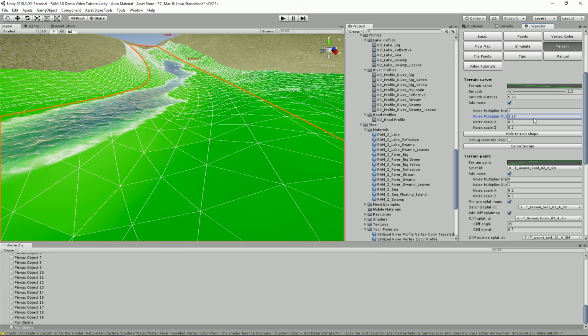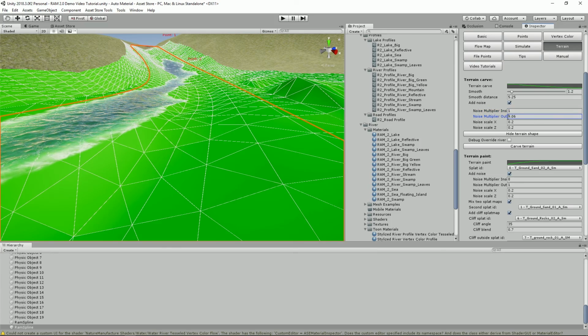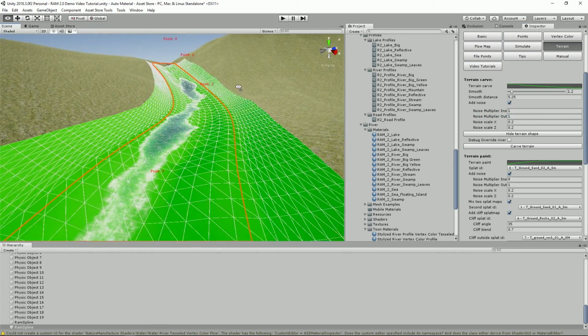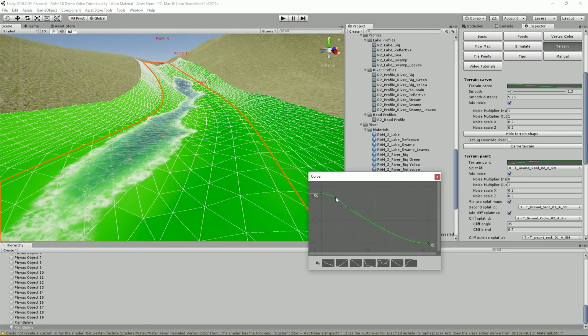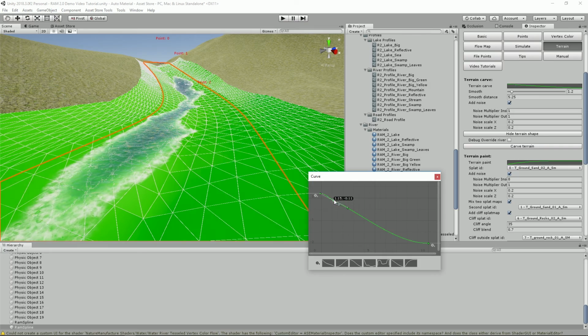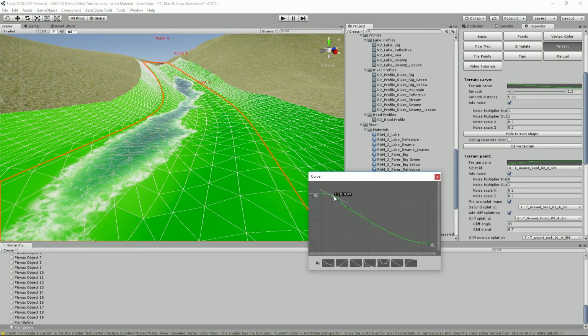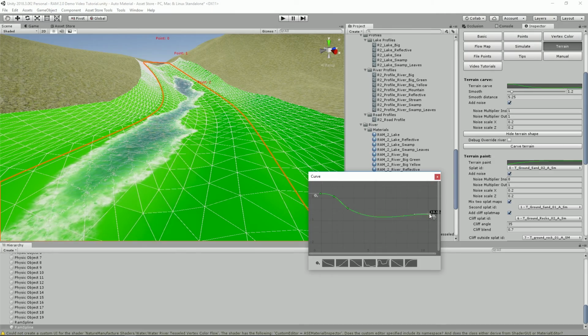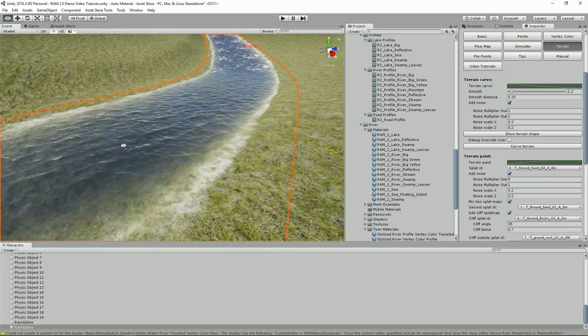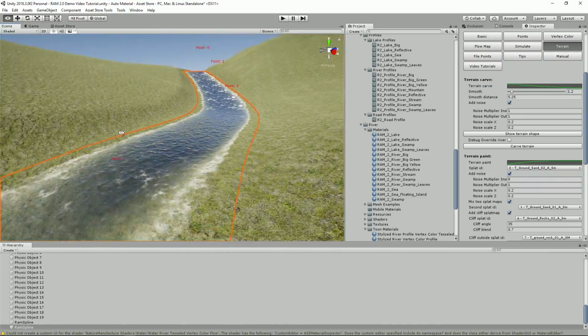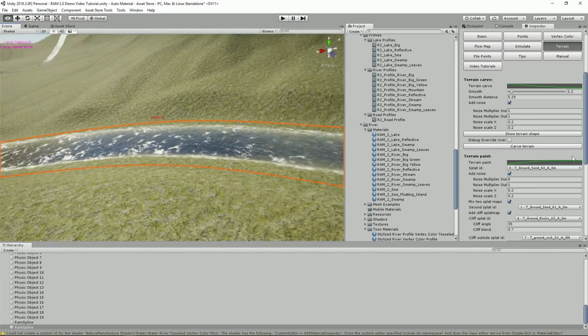Inside the spline and outside the spline noises are separated, just because it gives more control over this. We could change the spline shape and we see how it will affect our riverbed, right? Because the whole future shape is on spline. We click generate and we have nice looking terrain which was carved by our river.